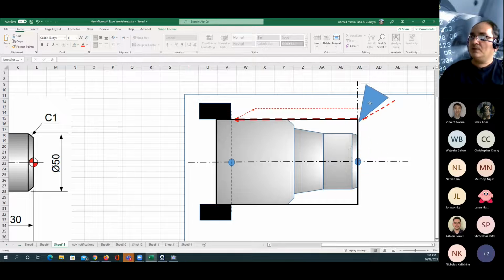So the cutting tool will simply remove a layer from the work part. Going to the center means that the whole face has been cut, because once again, the part is rotating. So now I cleaned the face. I set the length of the work part exactly as I wanted. Now we travel back and then we go up again. And now we are going to start the process of shaping the work part to reduce the diameter.